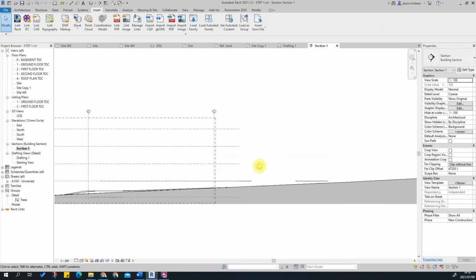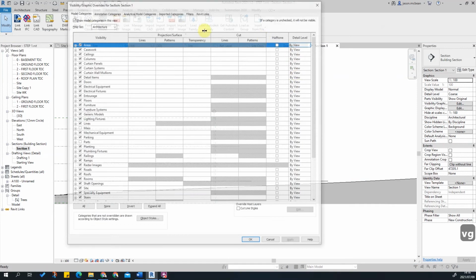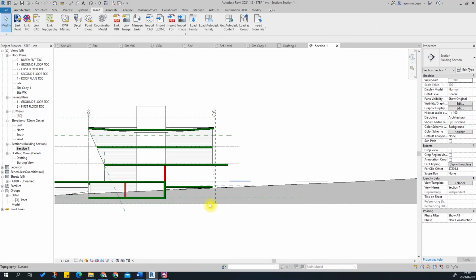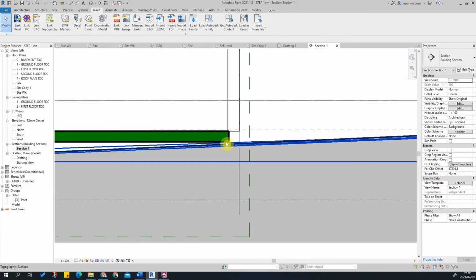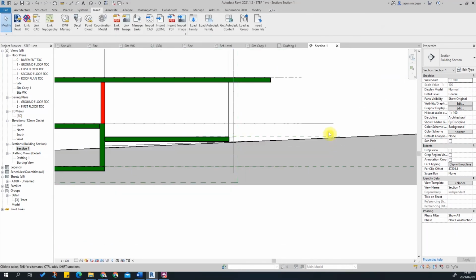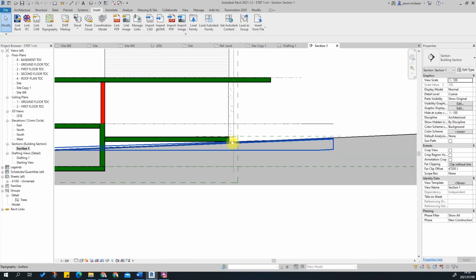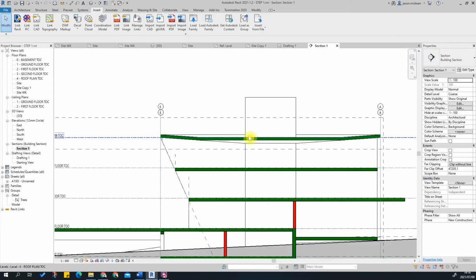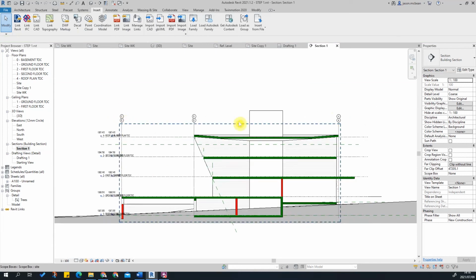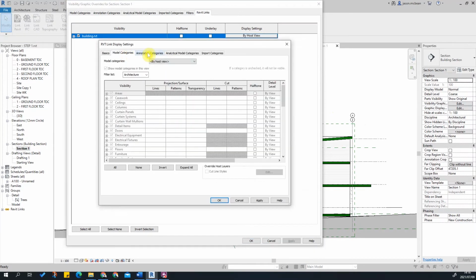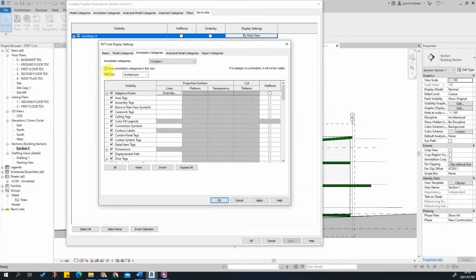Let's go to VG. Let's go to Revit links, and I'm going to switch this back on in here just for now. So it's pretty close. I just need to make the front of the building match. Here's the road. Here's the line of the road. And you can see our grids are also helping us now in this view. Okay. So let's just go to VG, Revit links by host. I'm just going to say custom, annotation, custom, none, apply.